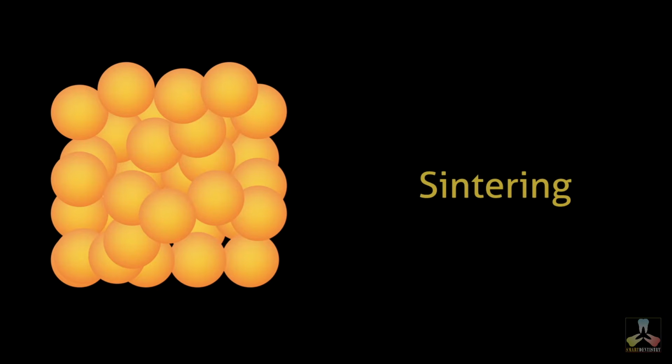These are two ceramic powder particles. Let's magnify it and take a closer look. Once the powder is heated, the surface of the powder particles melts and flows. But there will be no complete melting. This surface, once molten, will adhere to the adjacent powder particle to form a strong bond. This procedure of adherence is called sintering. So sintering makes the basis of the condensation technique. It is also the basis of most of the other ceramic processing methods.